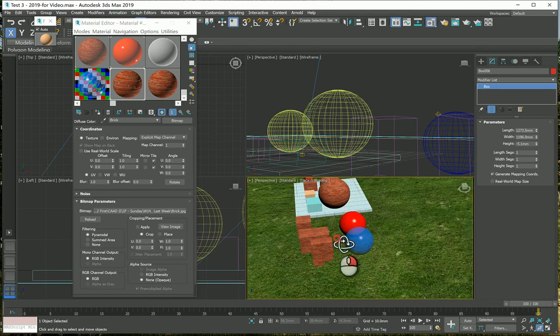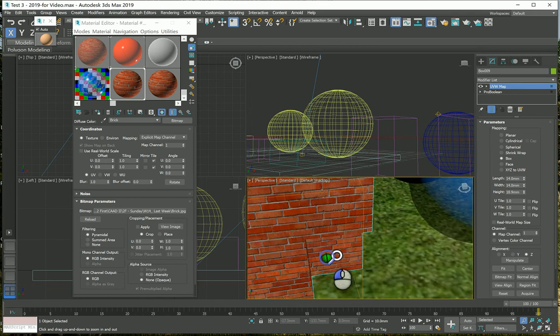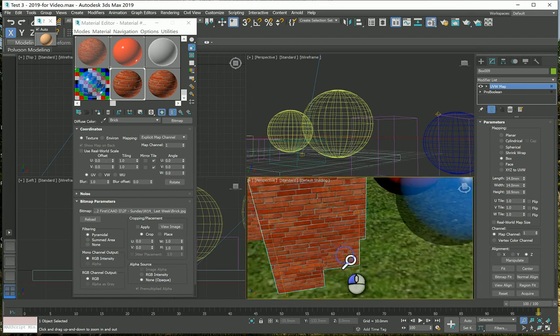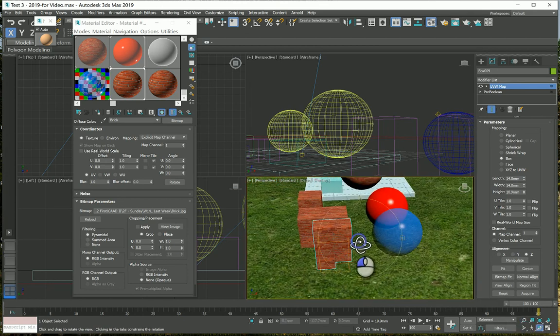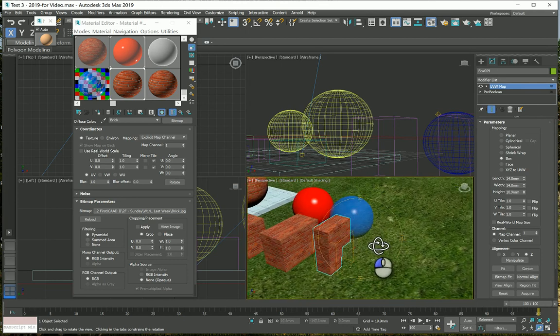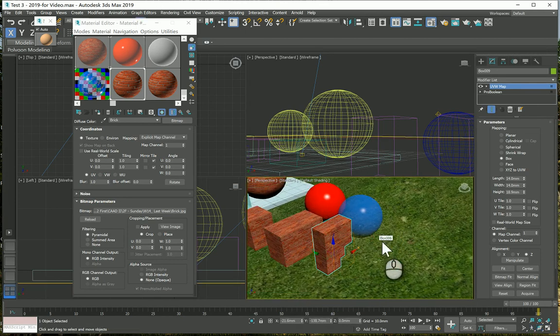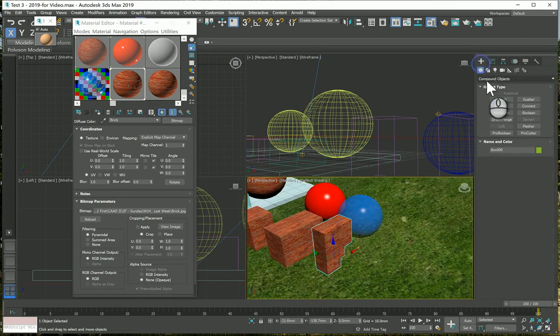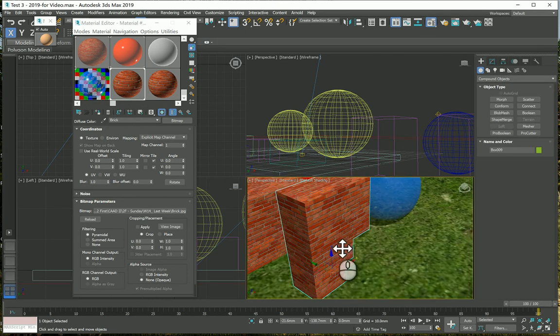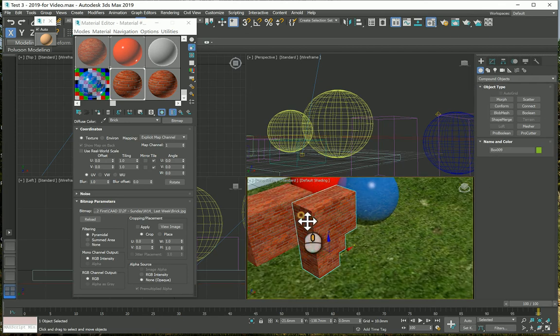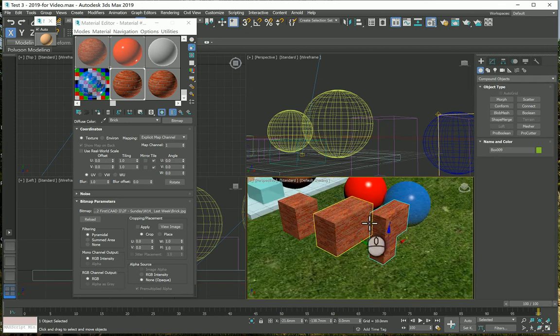So if you have the issue, which sadly didn't show here because of the boolean, usually the case is you're going to see the object has only the color of the brick, which is here in this case just brown, and you won't see the texture until you add a UVW map to it. So that's the second thing you might face, probably when you have a wall and you cut that wall, especially when you make the windows. That will give you a hard time with this case.